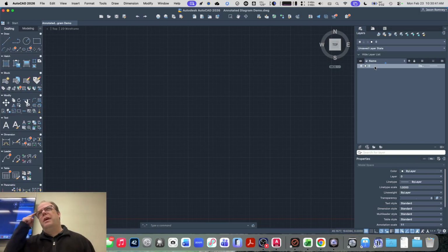If I'm trying to figure out how I'm going to do this, sometimes just cracking open AutoCAD for a minute and doing a quick little diagram of what I think helps me work out the details. It may not ever be a drawing I show to anybody else. I just need to take a half hour and draw this out for a second. In those cases, I'll draw on layer 0 because I'm not going to spend a lot of time on this. I'm never going to show it to anybody. I'm probably not even going to finish the drawing.